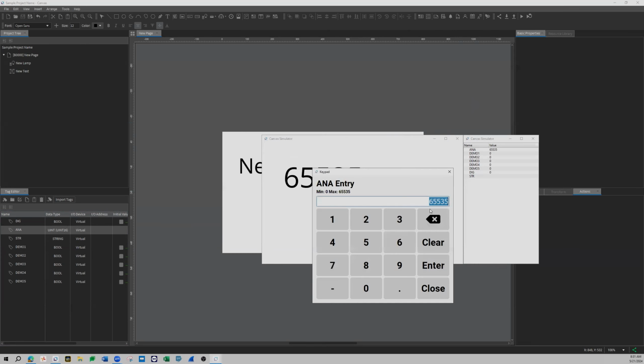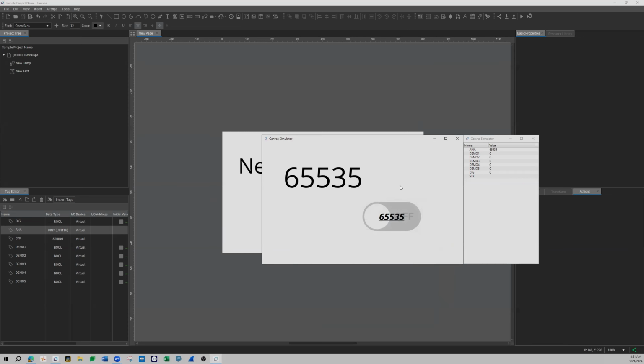So there we go. And then if I try to increment it by 1, it does not like that. It's not going to allow me to enter that number because it's outside the range. All right. So just your min and your max should be parallel with the values that you choose inside your tag. Don't make the same mistake I did. I mean, it'll be obvious because you'll see a message at the bottom show up saying, hey, this value is not appropriate for that tag. All right.